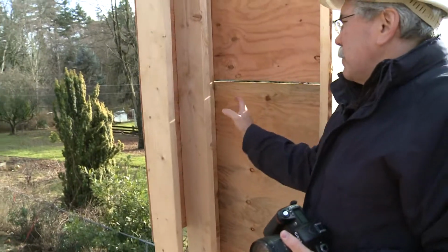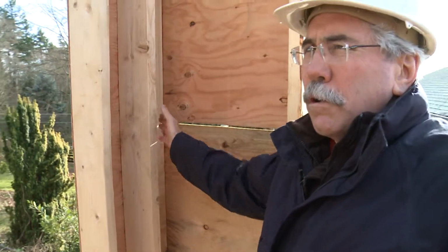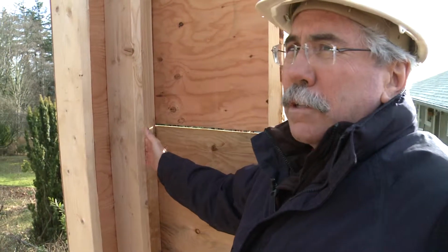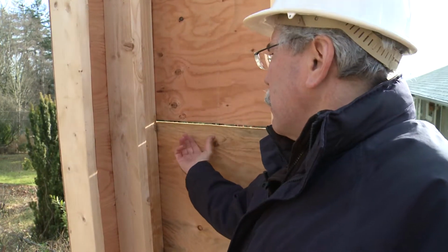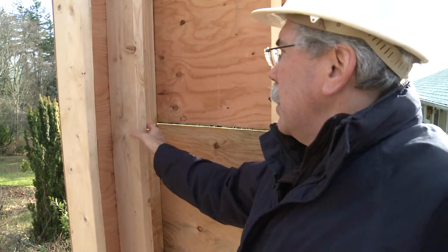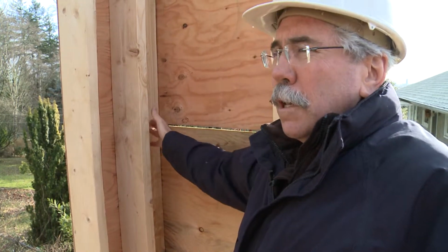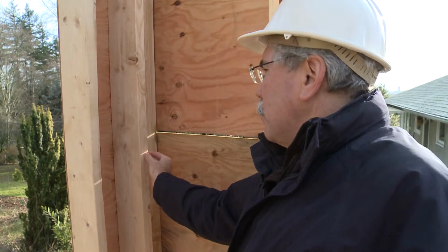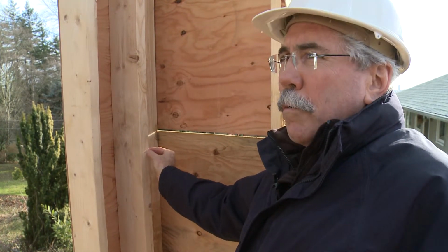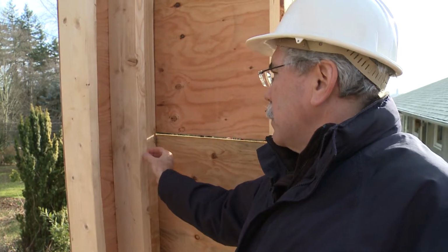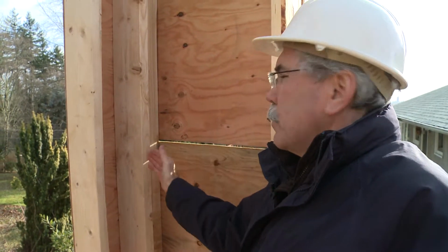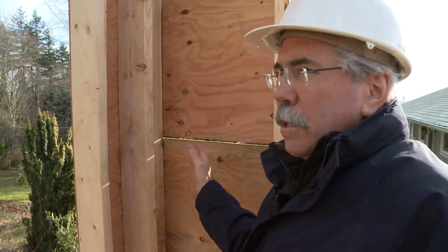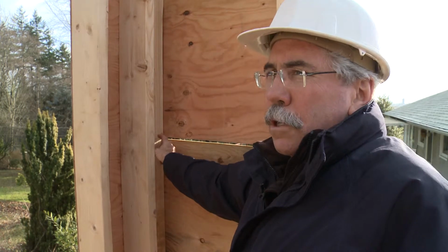Another feature of advanced framing is what we call a two-stud corner. Typically in wood frame construction, what we'll see is 3 studs used in a corner, so there'll be another stud here to back up the drywall. But in this case, we're using just 2 studs, and this allows us to get the full insulation in this corner. To support the drywall, we use things called drywall clips, which are fastened to this stud, and they catch the drywall rather than having a piece of lumber here to catch the drywall. So again, that reduces the amount of lumber and allows us to get more insulation in that area of the wall.